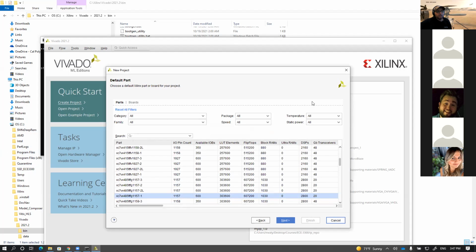What do you mean by constraint? Constraints are the parameters or variables, a set of environment settings that need to be set up on the project so it will succeed and be deployed on the chip. So one of them is to know what the input and output to the chip are. You agree? IO. In that case, IO is the XDC file. XDC file. Okay, I will show it to you now. Do you have any other question, Mohammed?